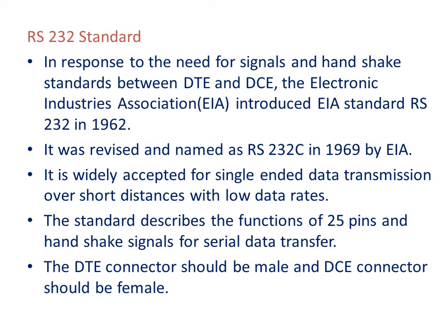The next topic is the RS-232 standard. Now here let us have the introduction to the RS-232 standard. In response to the need for a signal and handshake standard between DTE, that is data terminal equipment, and DCE, that is data communication equipment, the Electronic Industries Association, that is EIA, introduced the EIA standard, that is RS-232, in the year 1962.